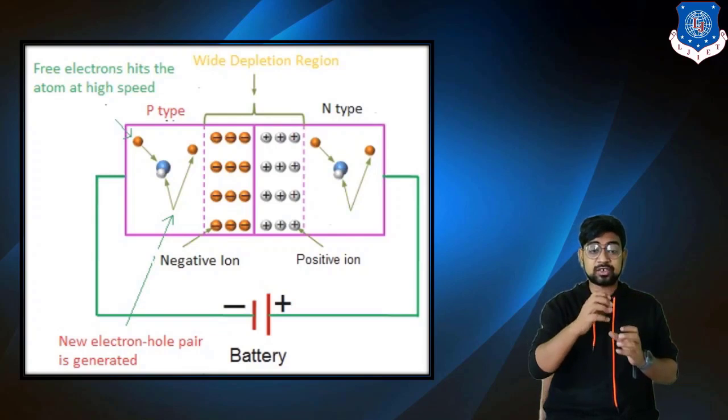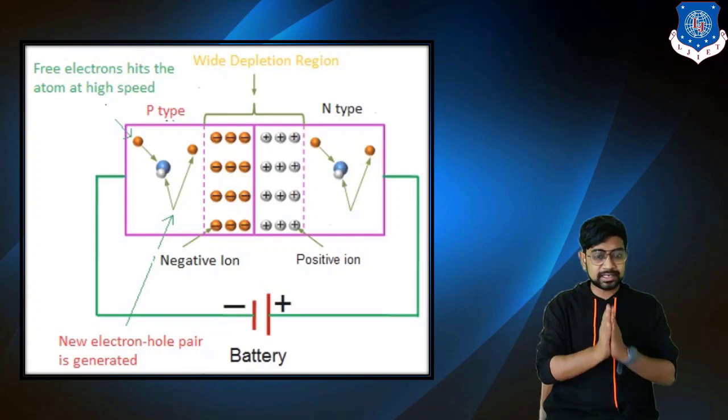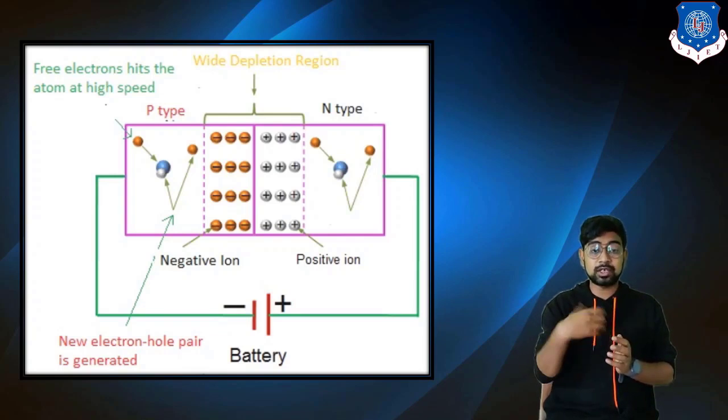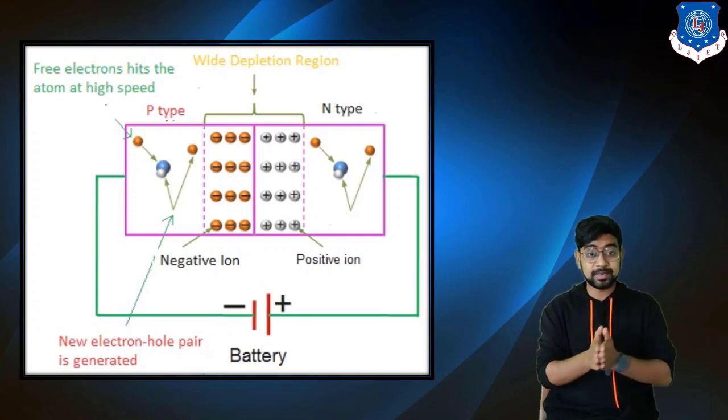As you increase the reverse voltage slowly and gradually, collisions increase, and after a certain point the free electrons start flowing despite the barrier. Though the barrier is there, they still flow, but once you increase the voltage more, the collisions produce heat and your PN junction gets burnt off. That is the only reason it doesn't return to its normalized position: it has been burned off.